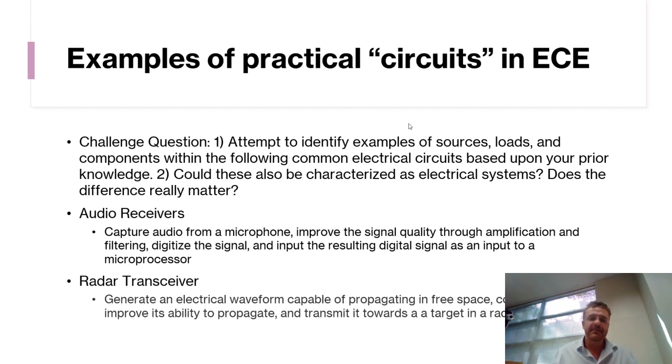However, that information is not going to be very useful when it comes out of the microphone. It's going to need to be conditioned in order to translate into a useful form. Maybe I will need to filter out other sources of information in that signal that I don't want if I'm trying to process only my voice. Maybe there's some background noise that I want to get rid of, or maybe there's just noise associated with the thermal behavior of the components. In that case, you would call that white noise.